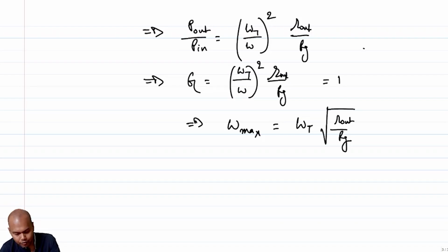Now at very low frequencies, where omega times CGS is very small, fine, you can make that assumption. But if you are anyway working at much lower frequency, you shouldn't bother about omega max. These values of omega max, just like omega t, are important when you want to push the frequency to higher and higher values. So that is number one sanity check.